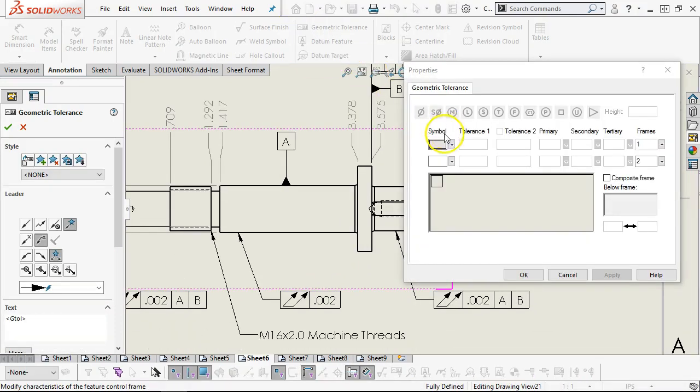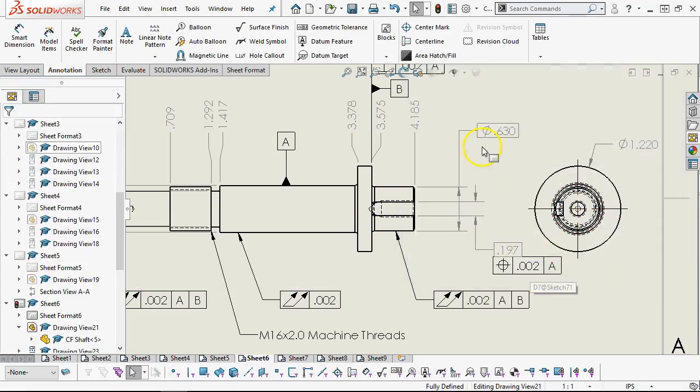Let's see if we can go in with a positional tolerance. Well, let's stay with the 2 thousandths. On the low side, there would be 1 thousandth clearance. On the high side, there would be 5 thousandths, just off the top of my head. So position to A, and then, well, let's go with that one for now.